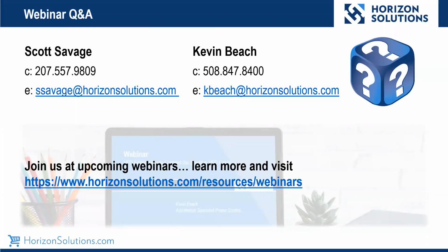Somebody else would like to know, what is CIV? CIV. Yes, Corona. Go ahead, Kevin. That is Corona inception voltage. That is the voltage that, in our case, the discussion here today, the motor windings need to get to for Corona to happen.